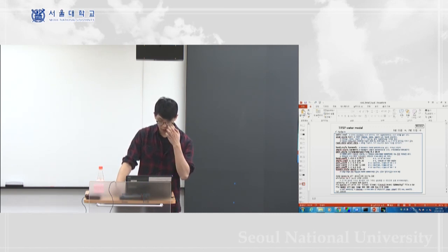You dump the movie file and you minimize the structure before you run these simulations with temperature, because it may be unstable at the first time. And then you are gonna use the fix print command to make it print out the density for you. And then it's gonna be an NPT simulation. And like I said, you have to be careful for the units, and the rest is similar.